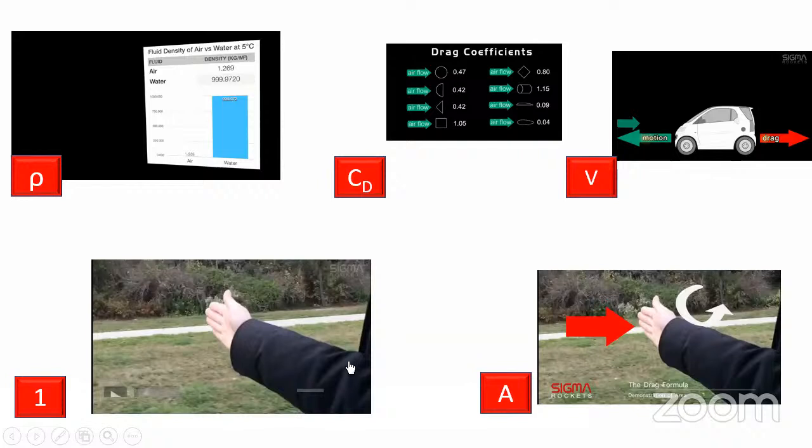The system which I have shown is not exactly for the bike. What I have done is I have tried both belt as well as chain. What I have noticed is the vibration will be more. When you run at even 20 kilometers per hour, or let's say some 400 RPM, you get a lot of noise. But in a belt-driven system, you cannot hear that noise. But there will always be continuous friction on the belt, so in the future, we need to maintain it. That is one part, what I think.